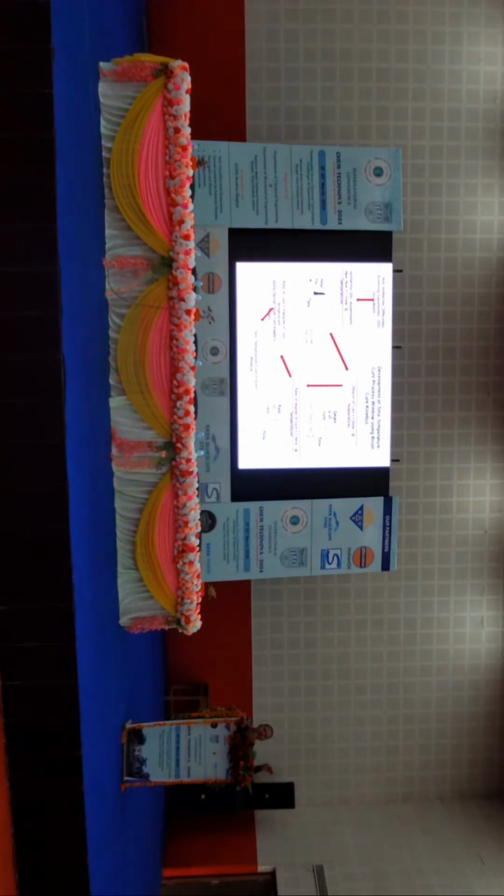If A reacts with B, it gives you C. It's a very simple elementary reaction. So what we do is follow the degradation of concentration of any of the species, and from that we model it. But in thermoset resins, you cannot do it that way, because it is a pre-polymer. The pre-polymers have different molecular weights and on site you will have different linkages happening. On the spot, many molecules of different molecular weights are getting engaged.